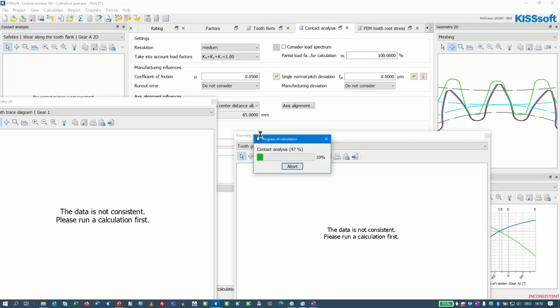For cross-axis helical gears, it's on the roadmap that we develop this. At the moment, we don't have it. The main difficulty there is that the tooth stiffness theory is virtually non-existent. And for worm gears, for the enveloping worm gears, like what you typically have in an industrial environment, the honest answer is, if we do it, it will take a long time. So at the moment, probably no.